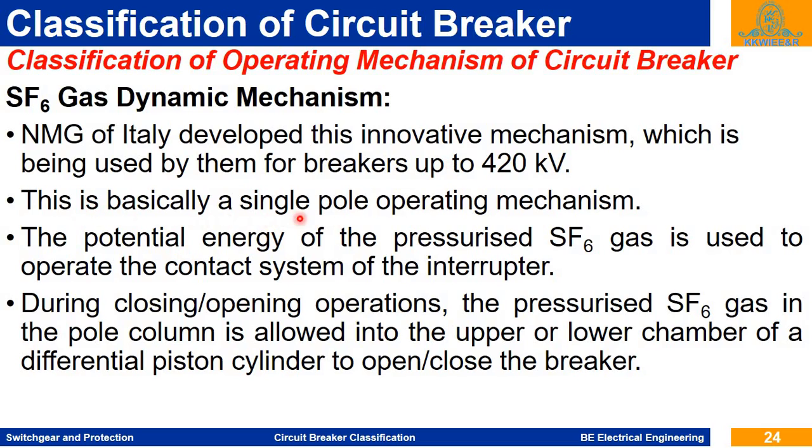It is basically a single pole operating mechanism, used for a single pole in the three-phase supply system. The potential energy of the pressurized SF6 gas is used to operate the contact system of the interrupter.